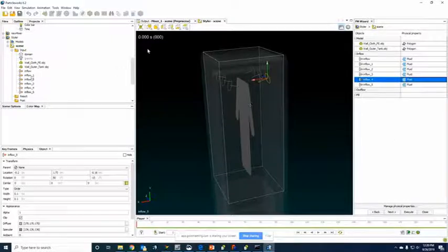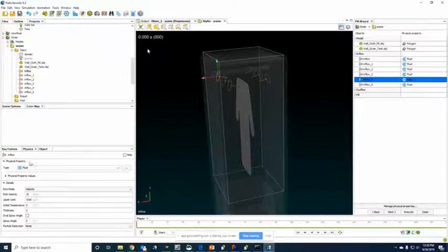All right, and then for each of these inflows, you can define how you want that to actually work. In our case, what we want to do is change the inflow velocity, the emit velocity, to 1 meter per second. We're going to do that for each of them. So 1, 1.